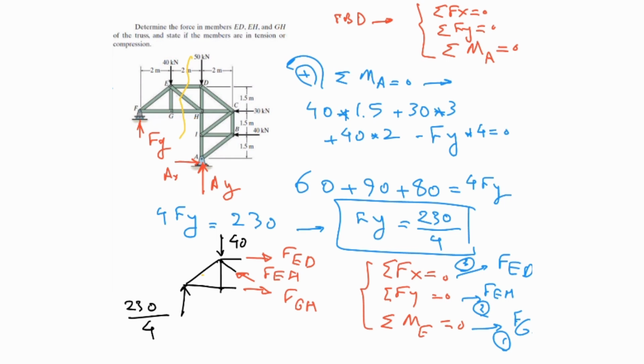As you can see, a problem like this is easy because we can find the line which goes through 3 links, and the other thing is that the free body diagram of the whole system is solvable because we have two joints, and one of them is the roller, meaning that in total we have 3 unknowns. This is the point of this problem and the previous one, and if you double check the previous video, you can deal with all kinds of these problems.